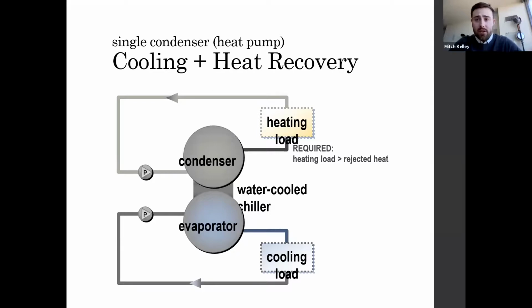Now, a standard chiller with no extra shells required can be used in a heat recovery application. This works well when a heating load exceeds the cooling load of the chiller during most of the operating hours. This is more likely the case with process loads than with comfort cooling loads. A single condenser chiller is a good match in systems with year-round cooling and heating loads. Most standard water-cooled chillers can provide suitable condenser water temperatures for heat recovery if operated at even slightly elevated refrigerant condensing temperatures.